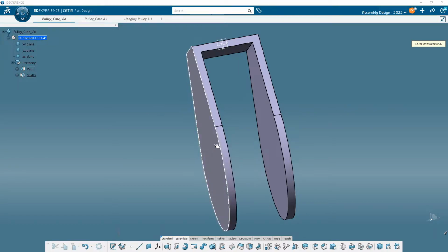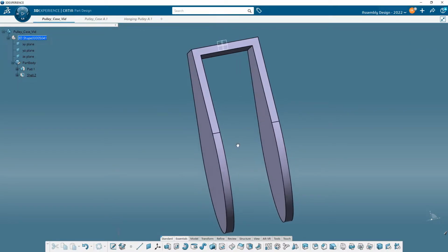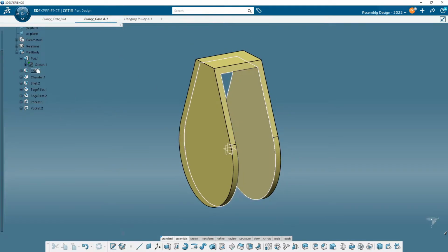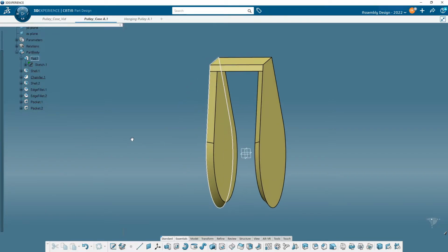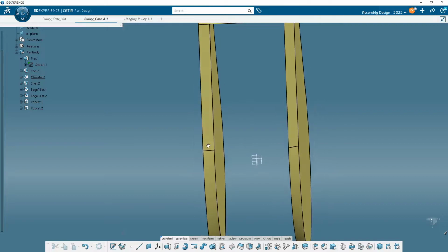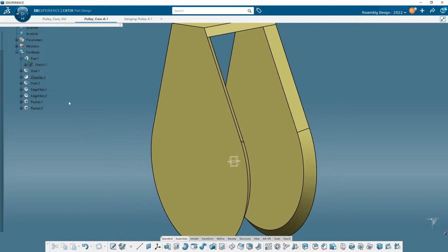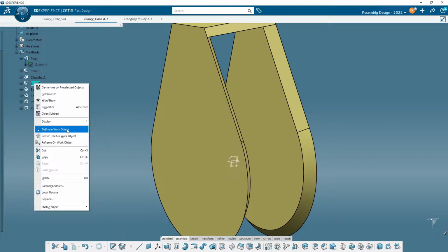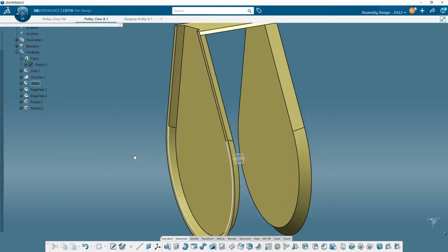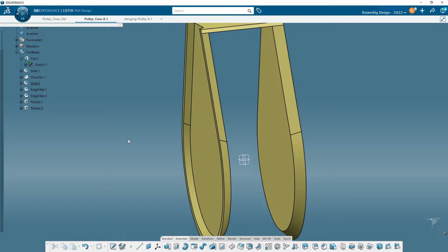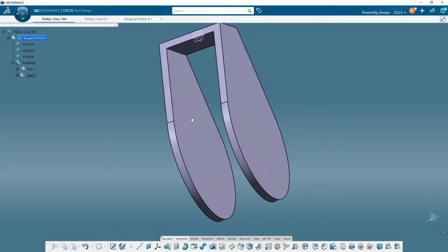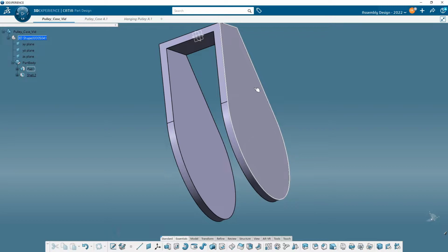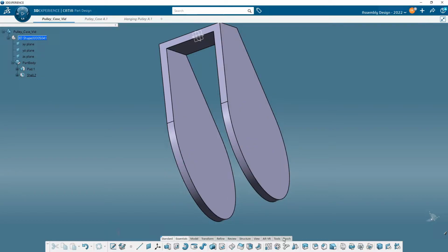Then the next part of this is also a little bit different. I need to hollow this section out here, but I need to have the angle on it that we have. Let's get this a little bit extra forward here. I need this chamfer right here, but I need it hollow. So what I want to explain here is why there's a particular order of operations in building this. If I went, well, okay, let's go ahead and shell this, because I want to have that little bit of hollow, and then maybe I think I'm going to add the chamfer afterwards.